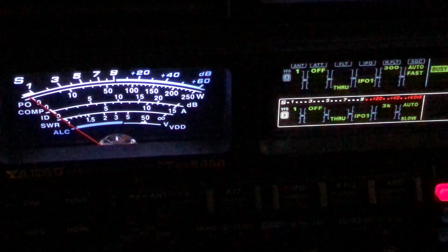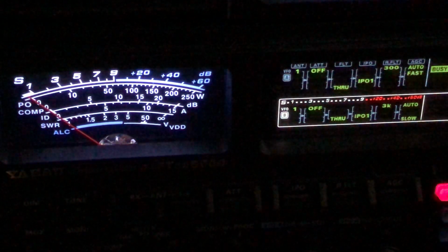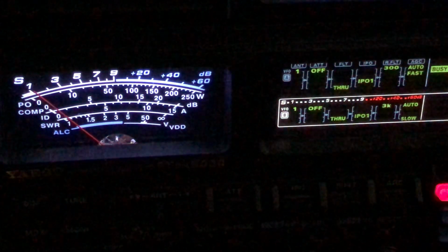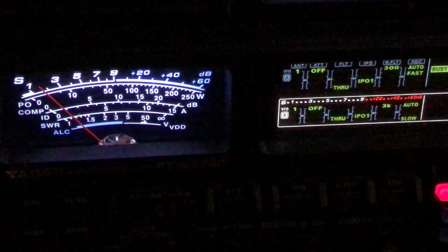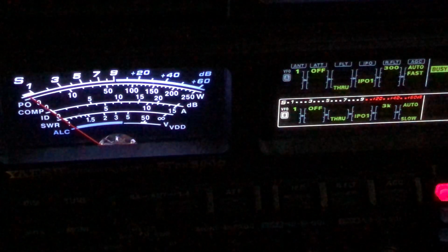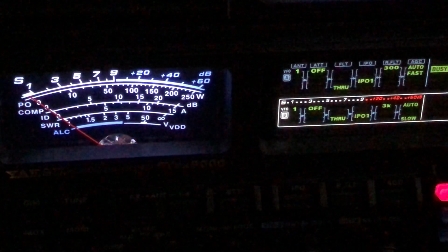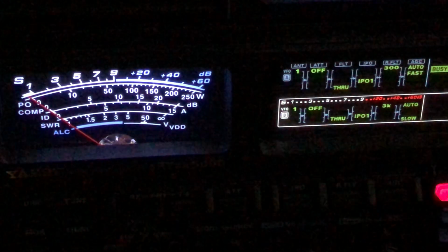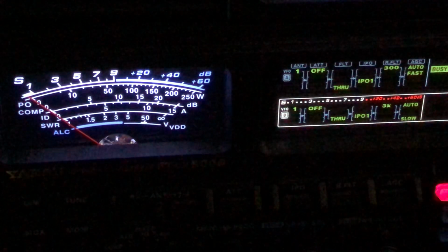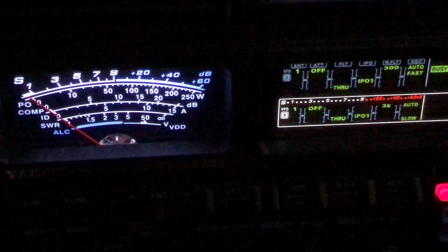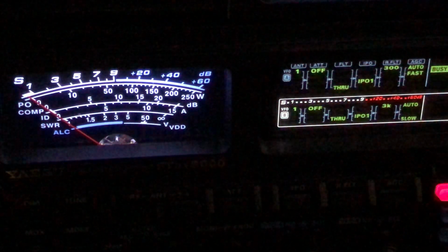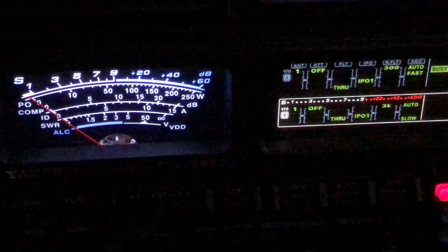So even when you think about back to the linear amplifier, that first 500 or 600 watts, it adds a lot of punch to your audio. Forget what the S meter does. It's what it does for your audio, your intelligibility. It really does make a lot of difference. Going from even 700-800 watts to legal limit, they're not going to notice much difference in your audio. And if they've got a meter that can register in 3 dB or 1 dB increments, they're going to see it move 3 dB, if it's an accurate meter. So there we are: decibels, gain, amplification, S meters, and how screwy they can be.